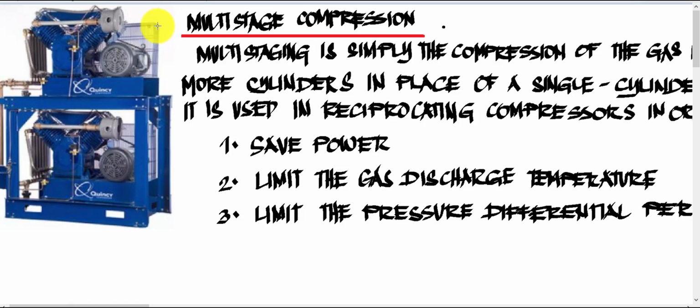I think this one is a heat exchanger to cool the air as it passes to the second stage of compression, where it can also be compressed in this upper part of the compressor. This saves power.